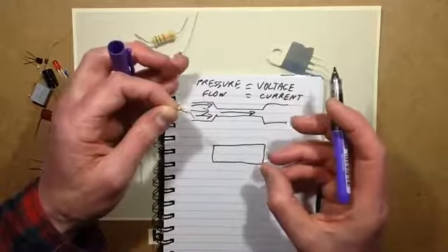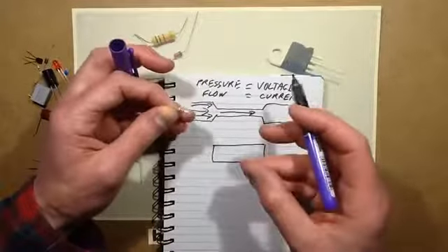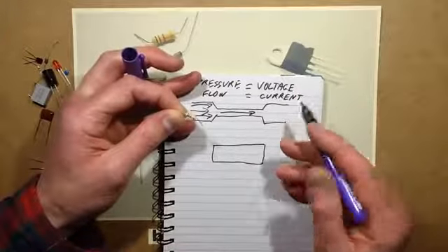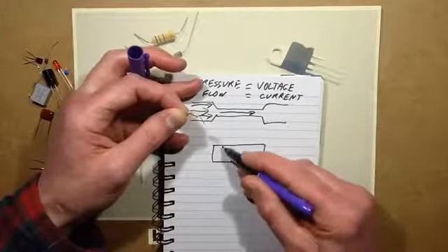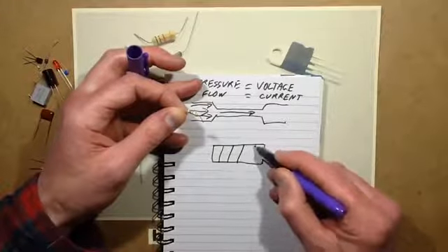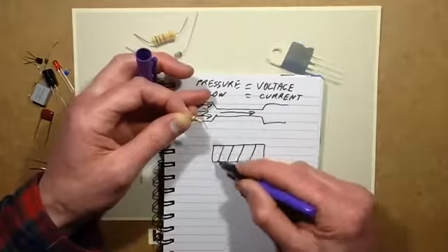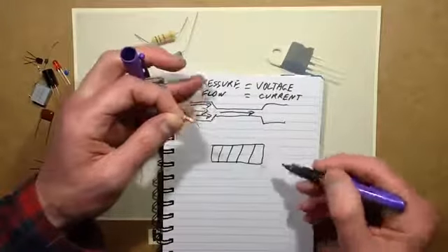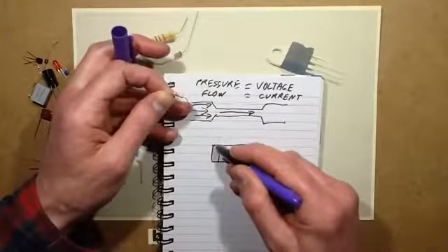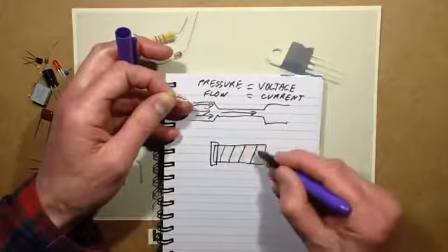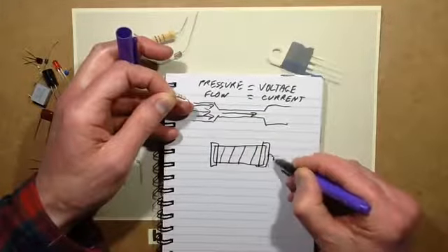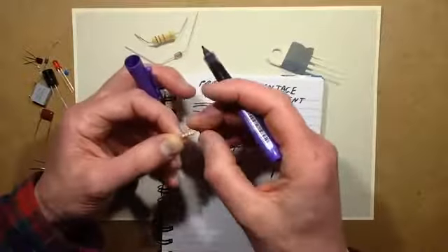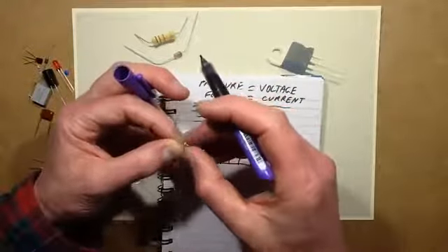And the thicker the carbon coating on it and the type of the composition they're putting on it, the more conductive it will be. But then they can fine-tune that. They actually cut a spiral round it, and that creates a long, thin path of the carbon, and that increases the value of the resistance. And once they've done that, they put a metal cap in the end, with the leads coming off, and they dip it in a sort of, I suppose it's a lacquer really.